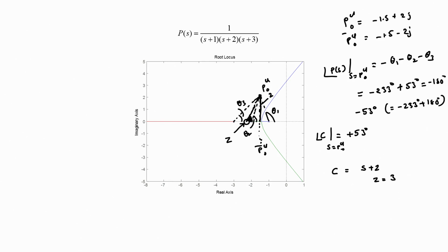This is all well and good, but there is one simple problem with this control structure, namely that it is not a causal controller. We have a transfer function here which has no denominator polynomial at all and just a numerator polynomial. So, it cannot be physically realized. If you recollect, we need physical controllers or physical plants to be strictly proper transfer functions or at best proper transfer functions, or in other words, the degree of the numerator polynomial should be less than or equal to the degree of the denominator polynomial. It cannot be greater than the degree of the denominator polynomial.